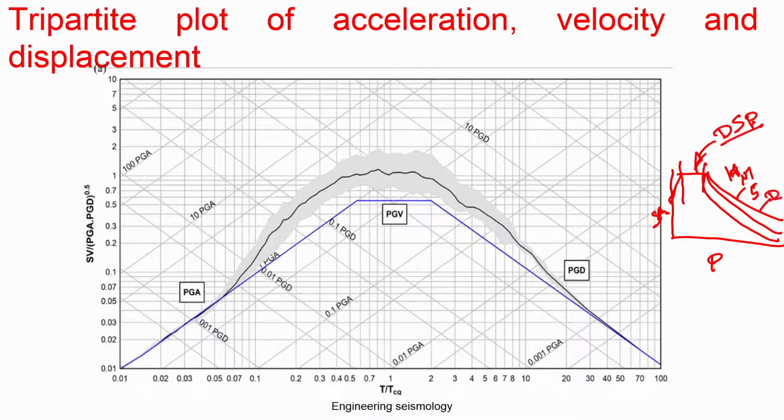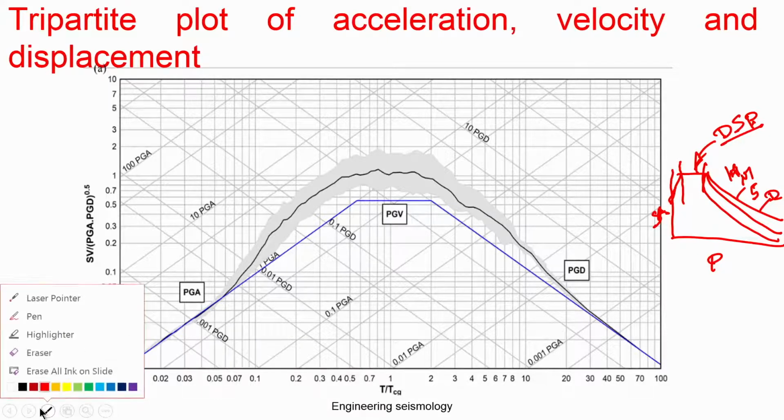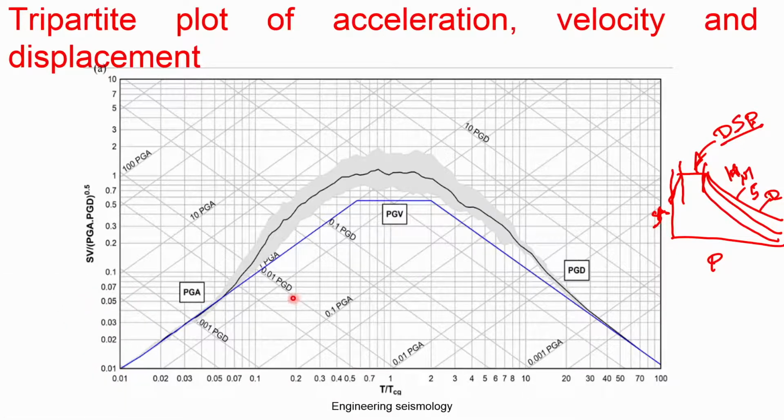this is the displacement. So, in order to get this picture, one needs to understand how this tripartite plot comes. Basically, you take the response spectrum data for a given site from different earthquake data, and after getting the response at a particular depth or surface level, you combine all of them. Here it is around 200 data. So, 100 and 200 data compiled, then you take the median. This median you draw as a single line. This is where you can expect a constant value.